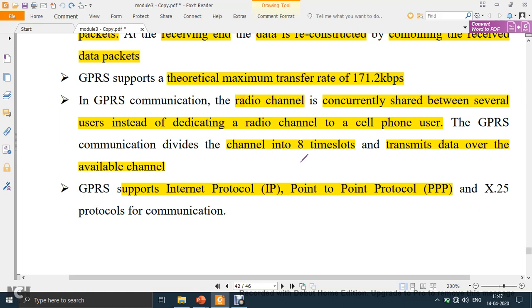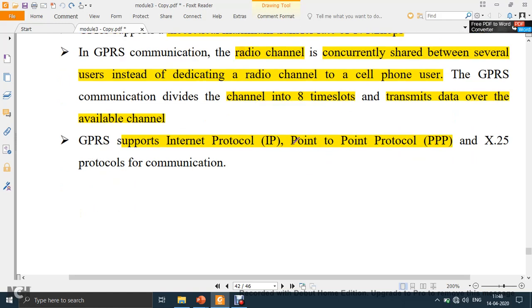It is just like a multiplexer. What does a multiplexer do? Let's say it is a 4:1 multiplexer. There are four inputs and only one output. That one output is shared by all four inputs based on the select line. Based on the value of the select line, which input will be communicated to the output is selected. Similarly here it is time multiplexed. Every user will be given a time slot within which he has to transmit the data.